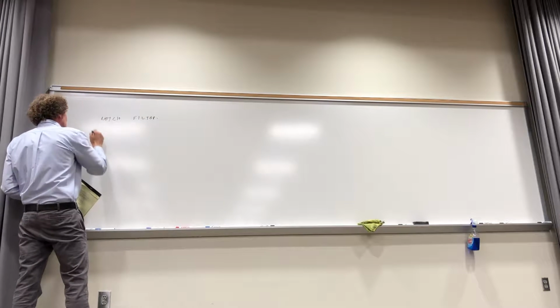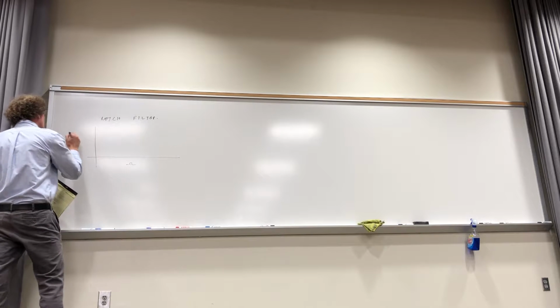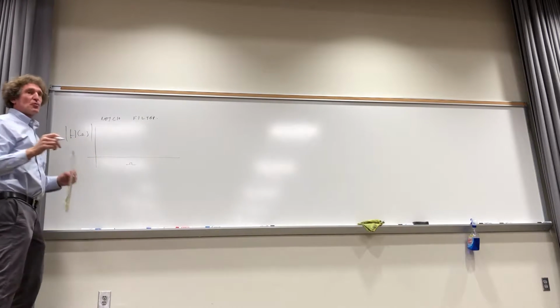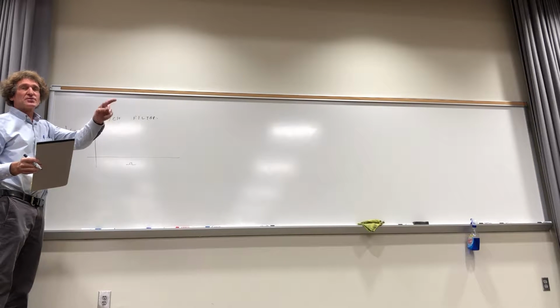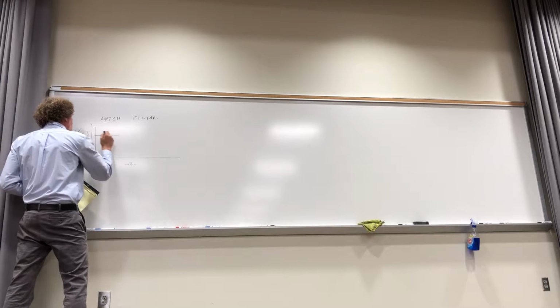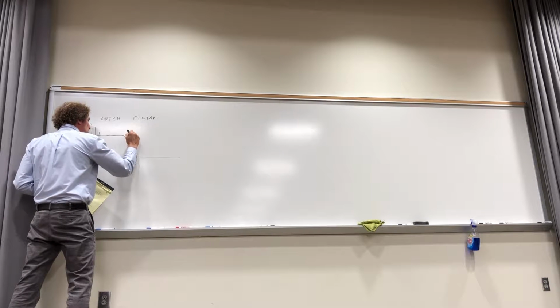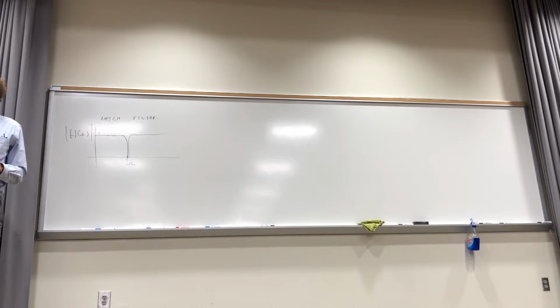What we're really talking about is this. If this is omega here, we're talking about a notch filter, this is h of omega. This was shown wrong on the actual graph when I was doing the presentation. It's right on OneNote, but I showed you the inverse of this by accident. But a notch filter should be about 1 all the way to the point where the notch occurs, and it should just stop that frequency. That's a notch filter in a nutshell. Does everybody follow me on that?